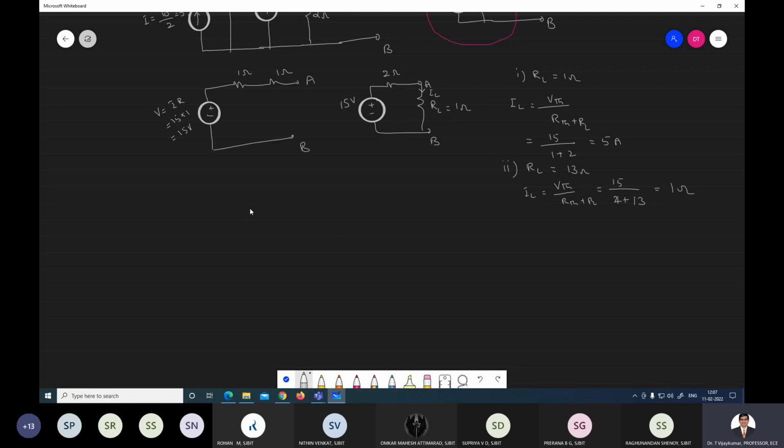So one voltage source is there, no? You have to short the voltage source. Resistance is there, that you keep, and open the current source. If it is open, there is no necessity of writing this, so that we will get a circuit like this. According to the procedure for RTH, short the voltage source, open the current source.